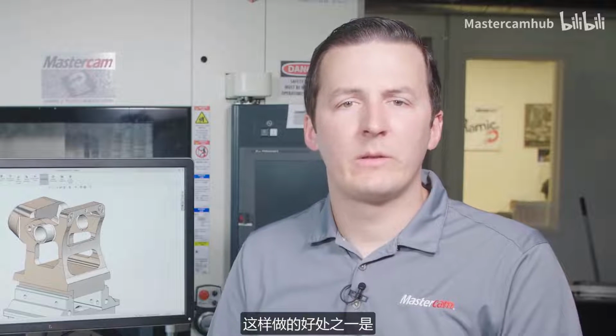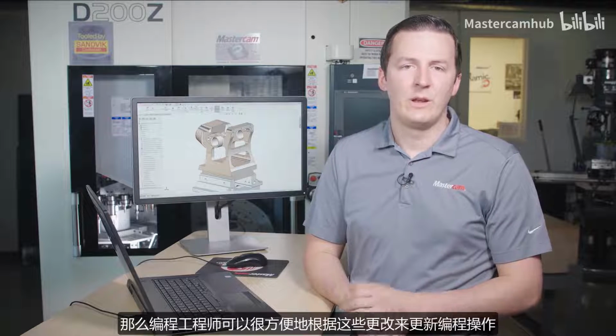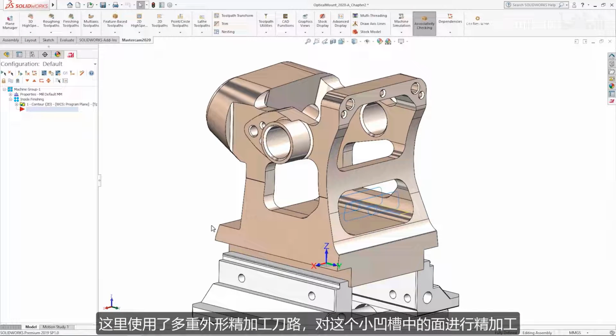One of the many benefits of this workflow is that if something changes in the design of the part, it's easy for the programmer to update any operations to reflect those changes. As an example, let's take a look at this simple operation on the back of the part. This is a multi-pass contour finishing toolpath, which is being used to finish the faces in this small pocket.